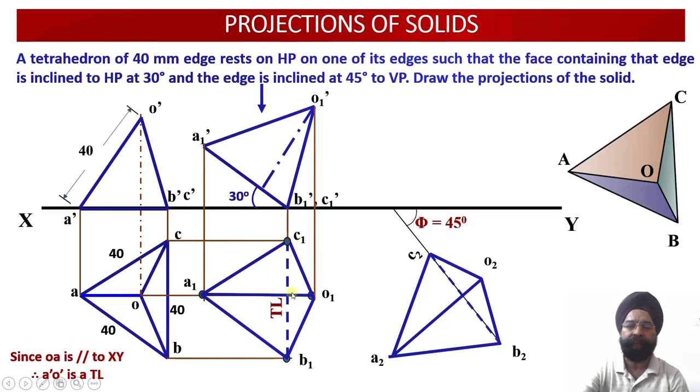So from points 1 and 3, automatically C2 and B2 will be located because there is zero vertical distance over here. From point 2, you go this much distance downwards. This will give you the location of O2, and you go in the other direction from this location to this location, measure the distance. So from this locus line, measure the distance of A1. You are going to get the location of the point A2.